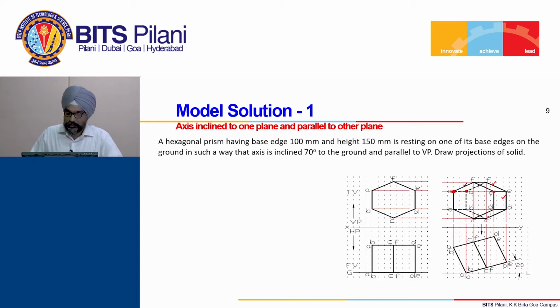So, whatever is not visible you have to show here. It is in isometric projection that the hidden lines are not shown. Here all hidden lines are to be shown. So, that is the distinction from the isometric drawing, and it also does not meet the requirements of the isometric drawing, but still you get some kind of 3D picture. You get the top base, the side as well as the front view, some additional views. That is why you get a little bit of 3D feeling. When you tilt the position of the solid, it is a common thing. Okay, so this is one problem we have seen.